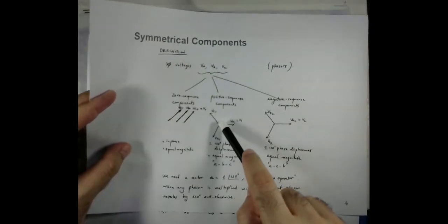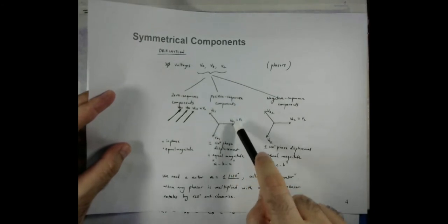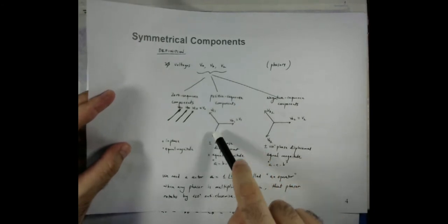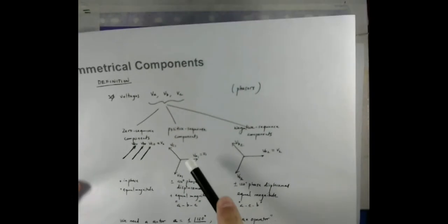So that will be equal to A square V1, because both have the same magnitude, but this represents the phase shift of V1 with an angle of 240. Similarly in the case of VC1, it is 120, as in the positive sequence A is followed by B and B is followed by C. So this is the positive sequence.